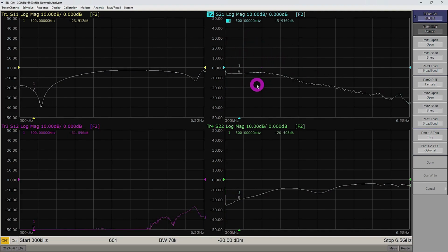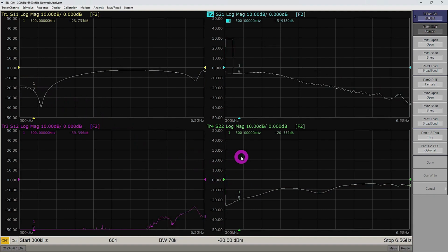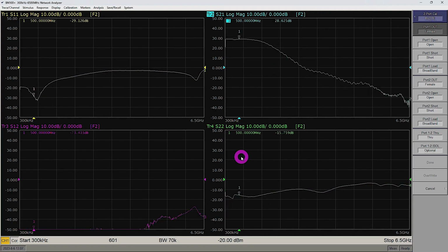And this means that we're going to be able to use this in an AGC loop, for example, to do automatic gain control. And the output return loss does change a little bit between the two states, but not by much. Most of these parameters are reasonably constant. Now I can go ahead and increase the frequency of this square wave. And normally what I would want to do is to trigger the VNA with this square wave so we can actually get a synchronized measurement, but it's not possible here because of a bug in the firmware, but we can change the frequency nonetheless. There you go.